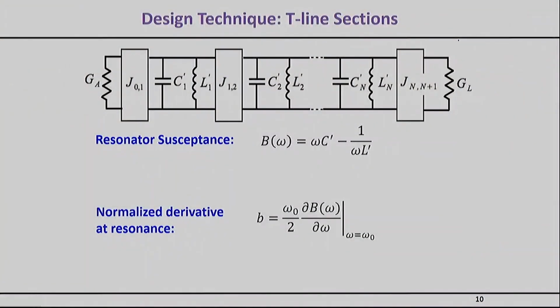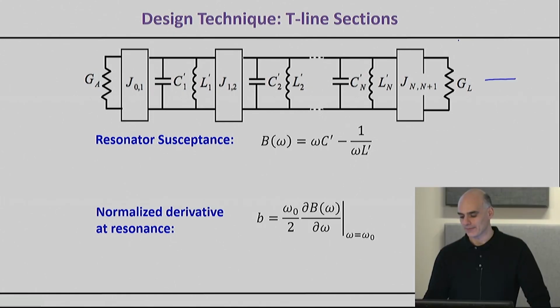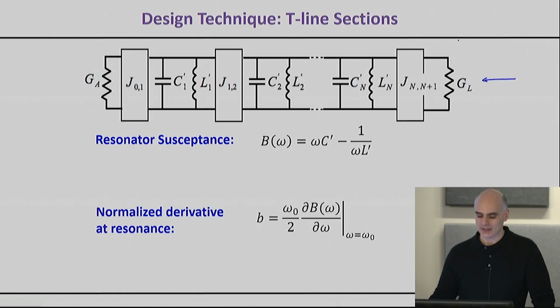All right, welcome back everyone. And we're going to go ahead and continue the discussion we have about the analysis and design of the bandpass filter based on transmission line and coupling gaps. So where we left things off is that we have been able right now to derive essentially our circuit, which is shown here with the J inverters and the resonators.